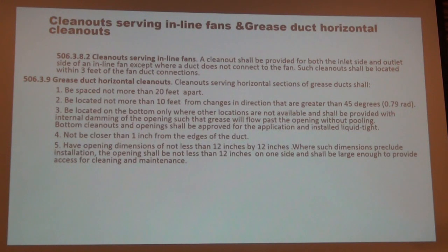So you're gonna be moving 3 or 4 items in order to get to the cap on the inside. Have you seen it where it's been done wrong before? All the time. Yes. So Ductmate is way better for cleanouts like these. You can wrap it with just a separate jacket, and then you just remove the jacket, remove the butterfly nuts, and get it out.